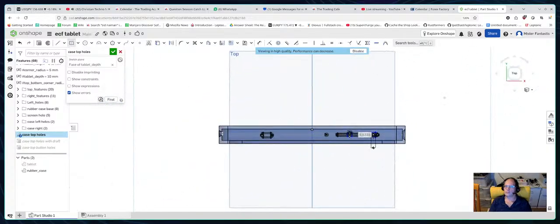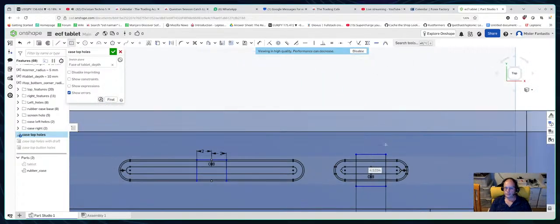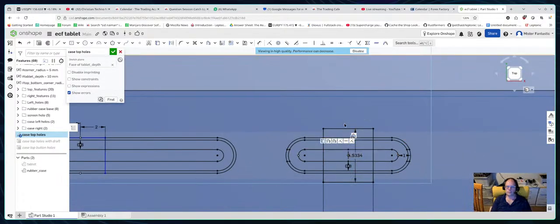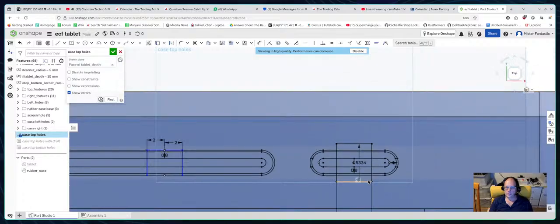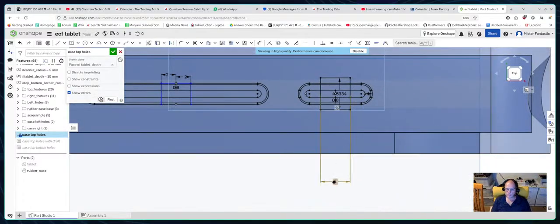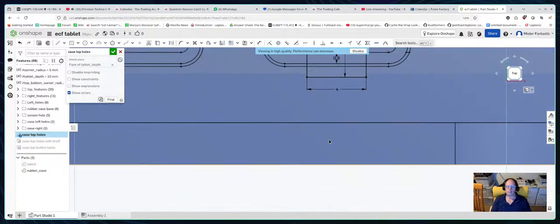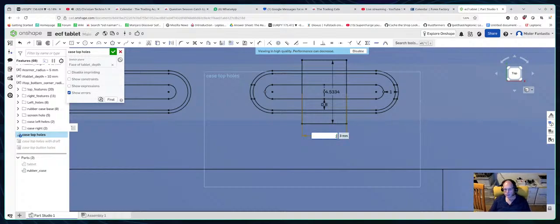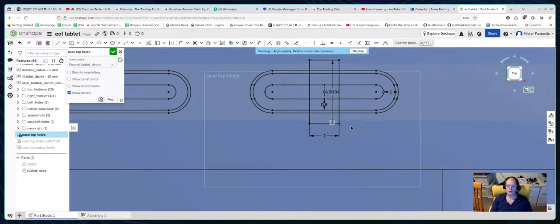Let's just go view top. That's brilliant. Okay, and then this height we don't care. And then we use the old trim tool. That 4 seems too wide. Wait. The dimensions are here. Why are the dimensions way over there? Come back. Maybe we should make it 3. I think it's 1.5 or 2 even. Let's make it 2 because it's a big button, you don't want too much rubber in the way stopping you pressing it, you know.